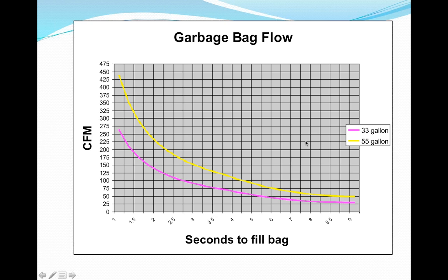volumetric capture method. And here's just a quick chart taking that seconds to fill with a 55-gallon bag and a 33-gallon bag. So you can see the range and kind of the resolution of airflow. You have to be pretty darn quick to measure something in the say 200 plus in order to be able to hit these half-second marks and to know exactly when it hit the pressure full indication.